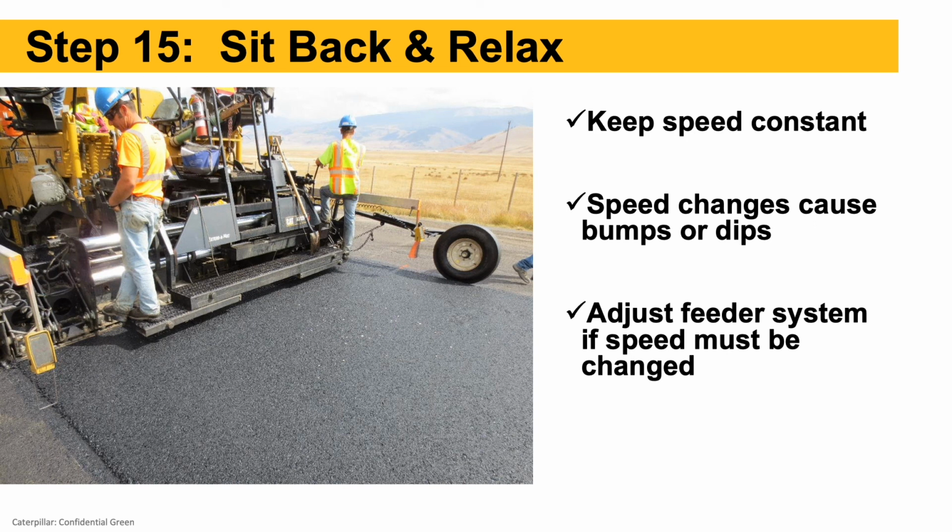Once you got all that done, just kick back and relax, right? Keep our paving speed constant, so just remember speed changes cause bumps and dips in the mat because head of material changes. So if we change speed, paver operator, first thing I need to think about as I grab that propel lever or speed dial to change speed is I should probably be changing my feed system, meaning conveyors, as well.